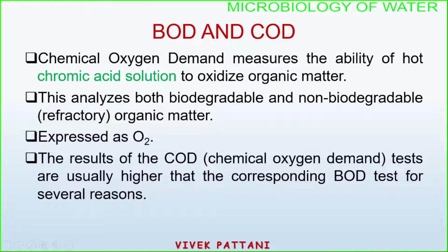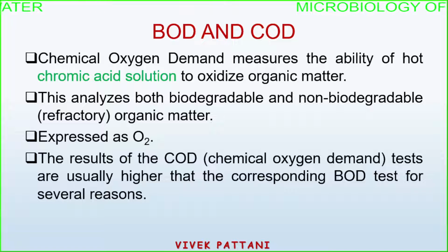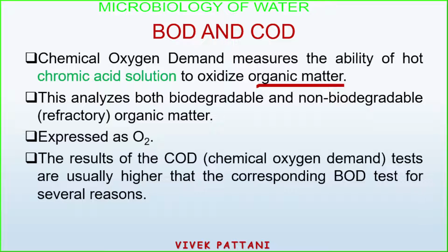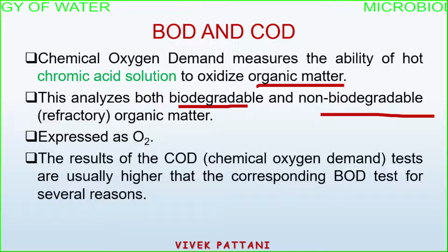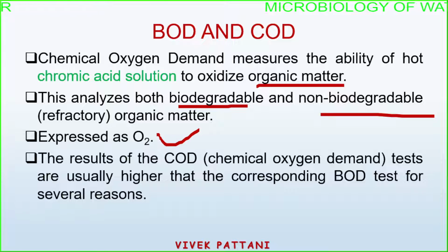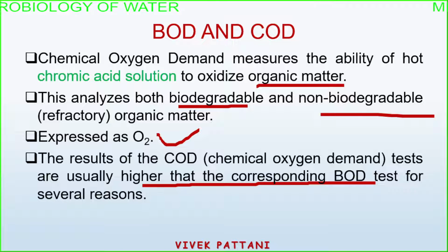Chemical oxygen demand basically measures the ability of a hot chromic solution to oxidize the organic content. It analyzes both biodegradable and non-biodegradable organic matter, which is expressed in terms of oxygen. The results of the chemical oxygen demand test are usually higher than the corresponding BOD test for several reasons.